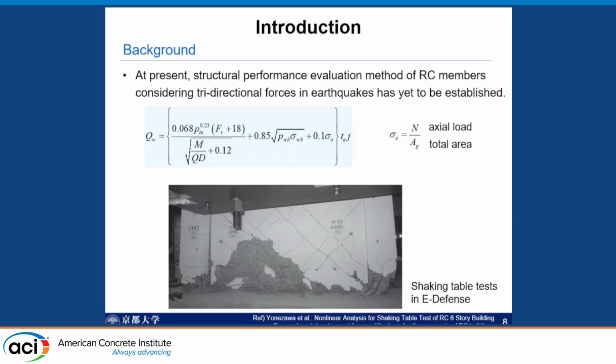You can see here the concrete contribution and the shear reinforcement contribution, or horizontal and vertical reinforcement contribution. And here you can see the contribution of the axial force. But we don't know how this axial force has an effect on the shear behavior of the wall.